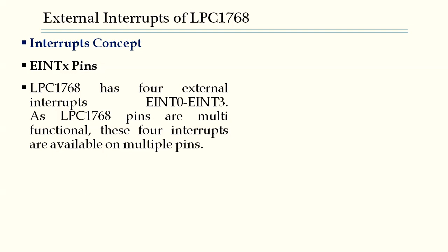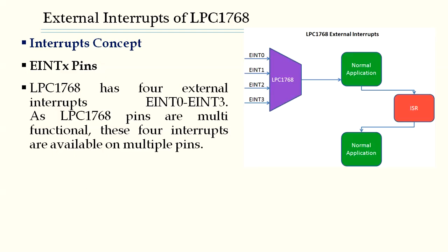They are not tied to just one pin; along with the different pin configurations, you would observe one of the functionalities to be either EINT0, 1, 2 or 3. Like any other peripheral that is multiplexed with a particular pin, so is the external interrupt.